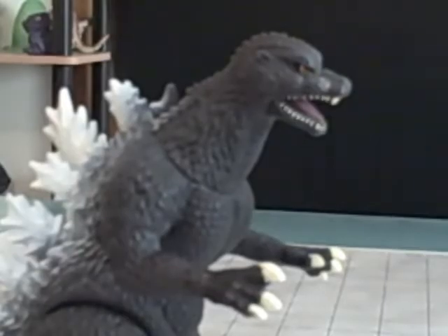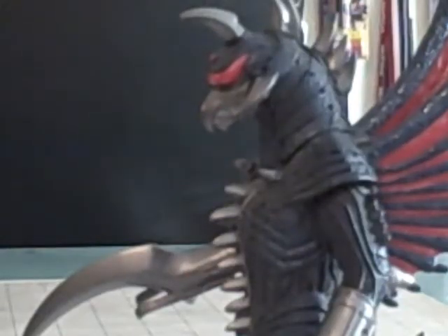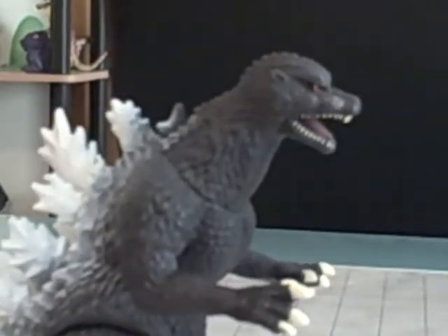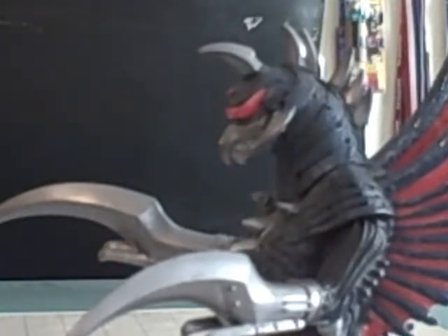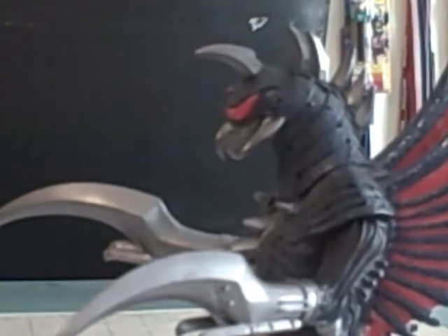Fancy dancy. Yes, and if you also look on the bubble map, we have hydraulics right here. Now, hydraulics is the study of fluids, the study of water or other fluids at rest or in motion, especially with respect to engineering applications. So it's really just like pneumatics, but with liquids. Exactly, Godzilla. Now let's get into hydraulic theory. Hydraulics cover the physical behavior of liquids in motion. They're pressurized oil used to get mechanical advantage, which is a big deal, and they help you do work. Hydraulics are shapeless, incompressible, and they're a great transmitter of force.